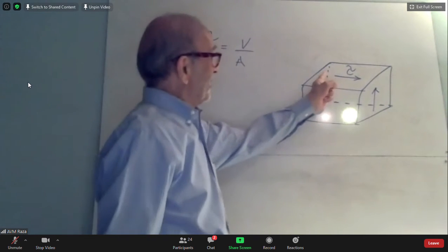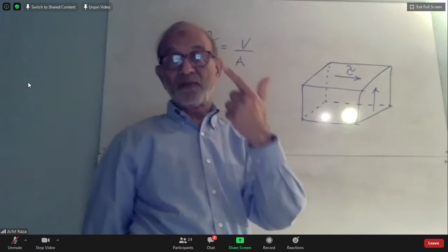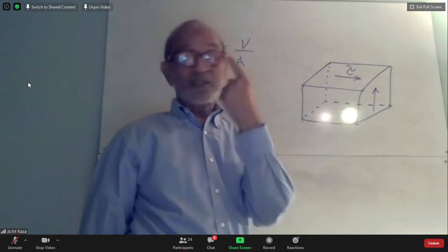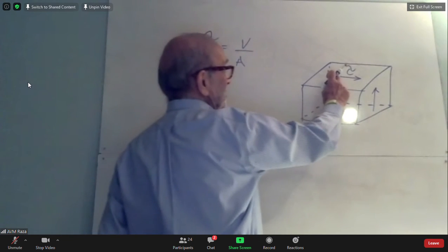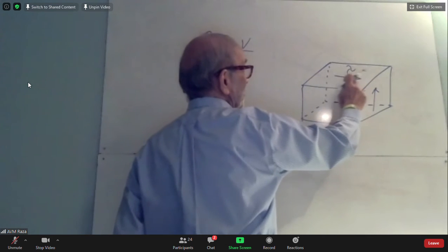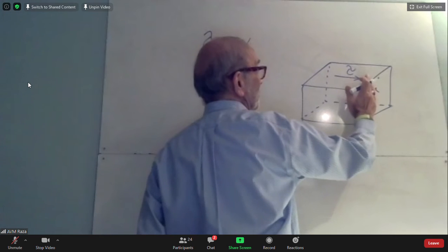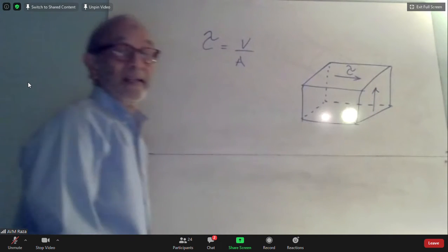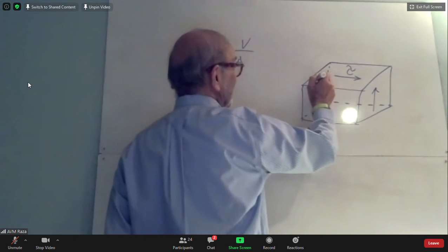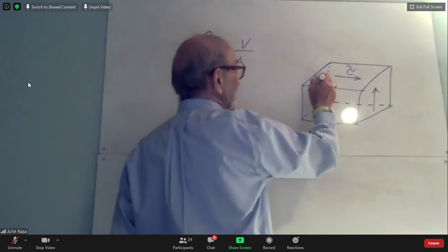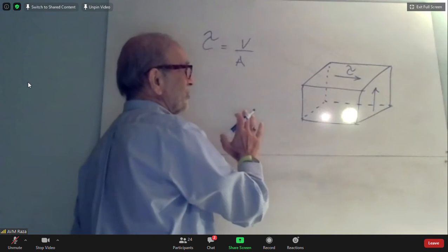So the bottom line is that shear stresses do not occur just on one surface. They have to be on more than one surface. For example, as I explained to you, if this is the shear stress on this face, then there has to be an equal and opposite shear stress on this face to keep it in equilibrium. And if that be so, there will be two more stresses to complete the equilibrium, which will be one on this face. So let me define those faces also.